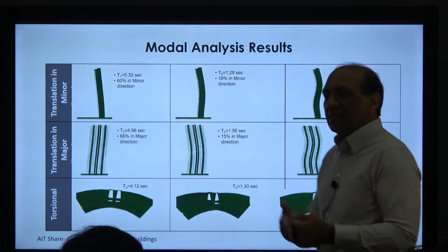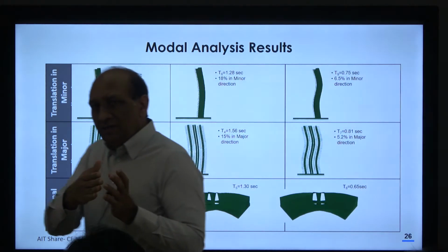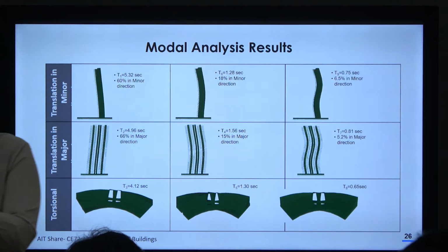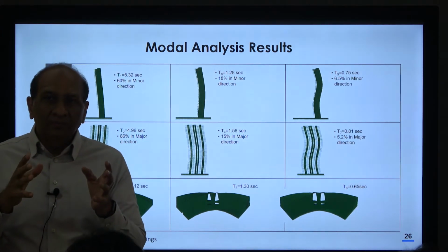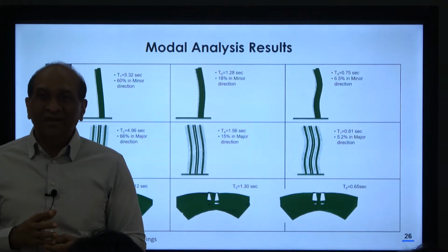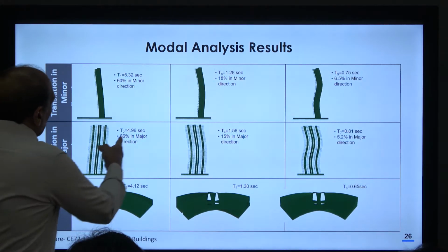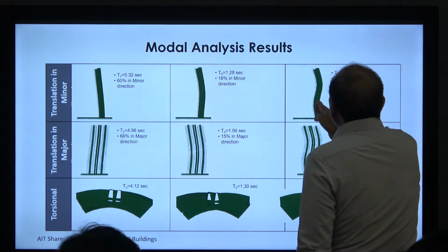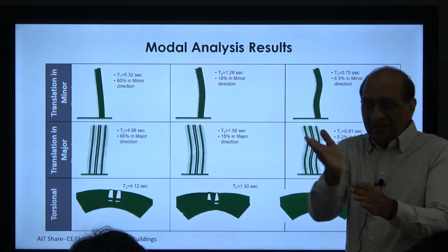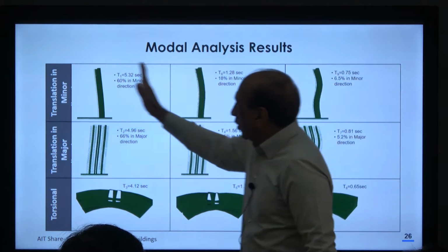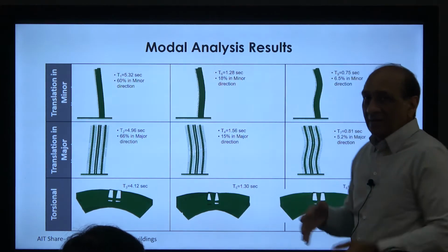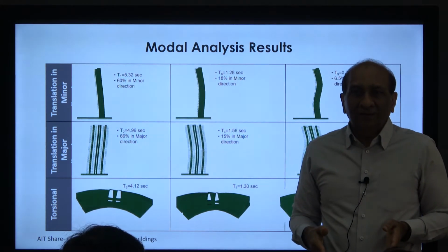So what is happening is that as we go along, as the natural period starts to be shorter, a lesser part of the building moves. And you can understand why. In this case, mass is not moving too much, because the building is moving a little bit here and there, but here all the mass is deforming. Here most of the mass is just remaining still, right?